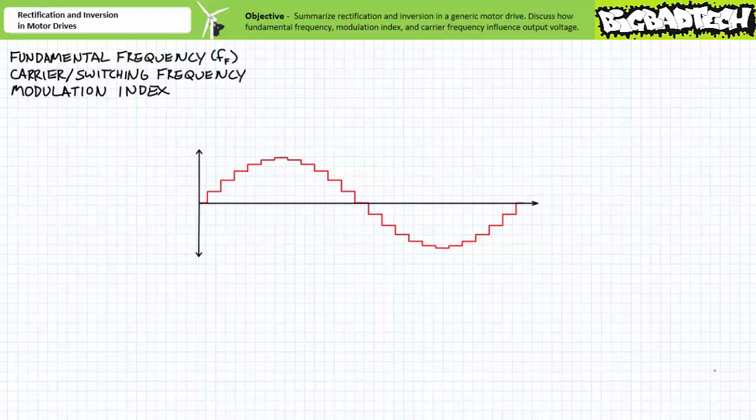In the interest of expediency, my simplified example is switching duty cycle at 24 times 60, or approximately 1.4 kHz. Switching frequency of motor drives can be 2 kHz up to 16 kHz, with those higher switching frequencies being better approximations of AC, however, coming at the expense of efficiency and necessitating more sophisticated control. These frequencies, by the way, are inside the audible range for most humans below 30. This accounts for the audible whine of VFDs that your ancient dinosaur of an instructor is incapable of hearing.